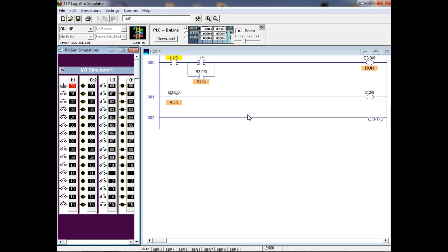The stop circuit, the stop button is supposed to be a what? A normally closed. Why? Because if the wire breaks, which happens all the time, you would not have the ability to do what? Stop it. But if we use an examine if closed and the thing breaks, right, you understand, then what's going to happen? It's going to stop. It's better to have something stop than not have the ability to stop.